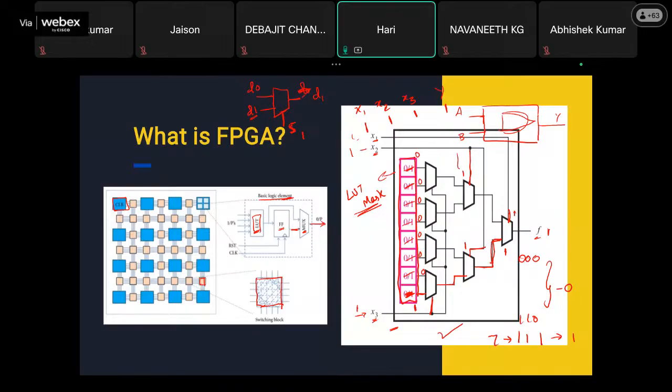Yeah, it is similar, but it is based on a very large scale. If you are just using a mux, it is not possible to store an element, right? So that's why they integrated flip flops and SRAMs, and there are RAMs to store the values of that register so that you can use them for later purposes. In short, it is similar, but with a mux you can realize some equations, but you will not be able to store a value. Here you can store a value because these FPGAs are loaded with some amount of embedded memory. So just using a mux, you can realize equations, but you can't do more things.